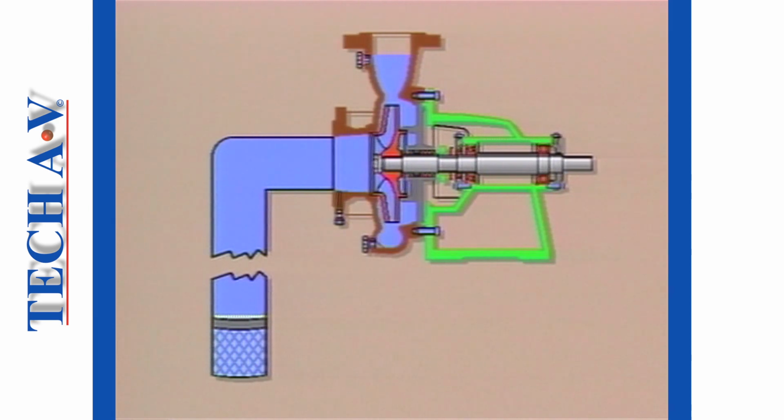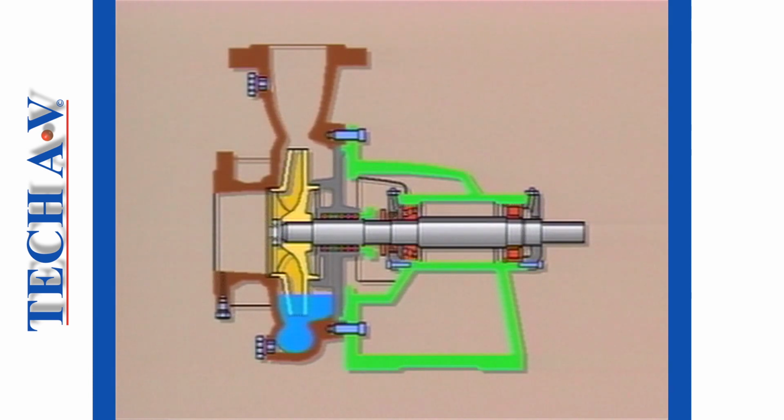Usually a foot valve or non-return valve prevents the fluid from running out of the suction pipe whilst the pump is stationary. A pump that is not primed will not deliver liquid, and prolonged operation under such conditions will cause extensive and expensive internal pump damage.